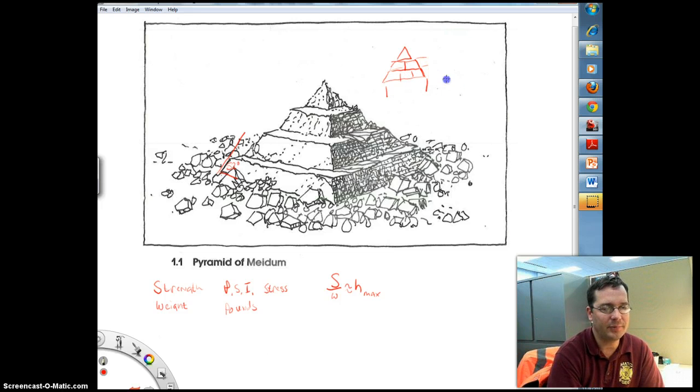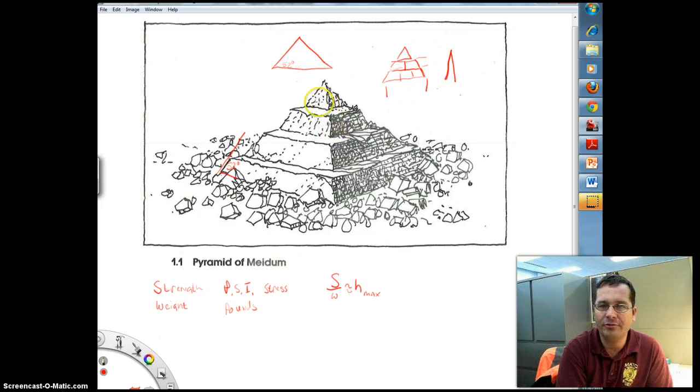So that you cannot build a pyramid that looks like a church spire. Limestone will not support this. Limestone requires some maximum slope angle that's pretty conservative. You can't build a straight tower out of limestone. It's not strong enough. What they figured out was that 52-degree angle that was used for this pyramid was too steep. The limestone was not strong enough to support the material above it at that angle.